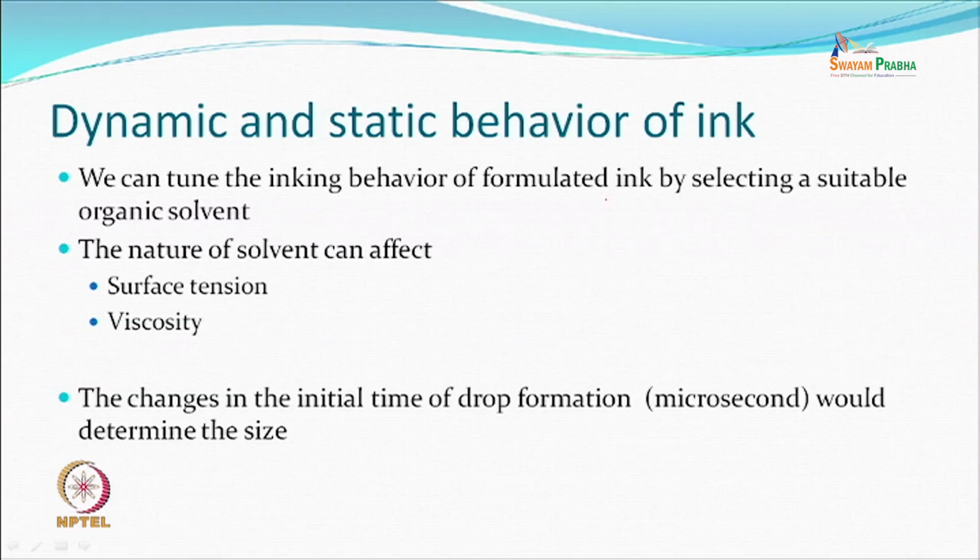Like the same water, when you spray at a faster rate, it sprays into atomized smaller droplets. If instead of water you had a thick viscous liquid, you might find it does not break into smaller parts because the viscosity doesn't allow them to separate. So these things happen in a very short time, and a small change is also important, and therefore this is a specialized area of making an ink.